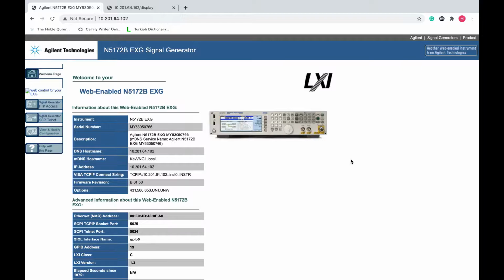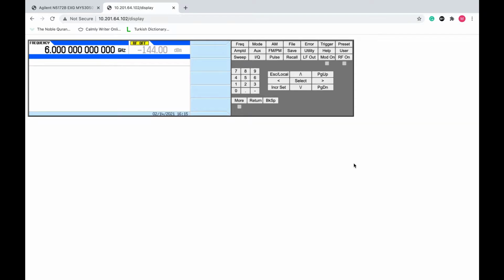And we will compare their performance using measurements like the spectrum, eye, and polar diagrams. Starting with Gaussian pulse shaping, we will see its effects in terms of spectrum utilization and ISI. We are asked to send an MSK signal with Gaussian pulse shaping.